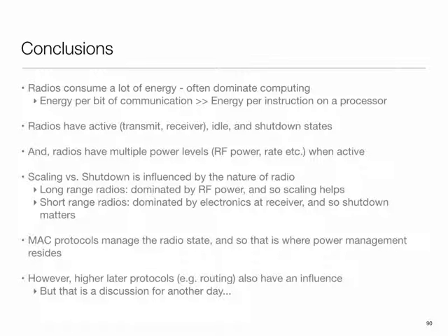What, on the other hand, 15.4 and Bluetooth LE, they all are based around the concept of having a frame, having some sort of schedule. 15.4 and Wi-Fi are based around having a frame and a schedule, and Bluetooth LE is based around the concept of basically duty cycling coupled with the packets coming through.